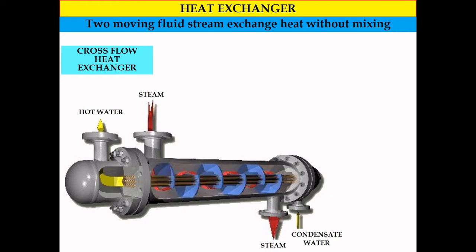So the temperature of the condensate water increases due to the heat transfer process inside the heat exchanger. The steam is considered the hotter fluid, and the condensate water is considered the colder fluid. Due to the temperature difference, the steam will transfer heat to the condensate water, so the temperature of the condensate water will increase after it comes out from the heat exchanger.